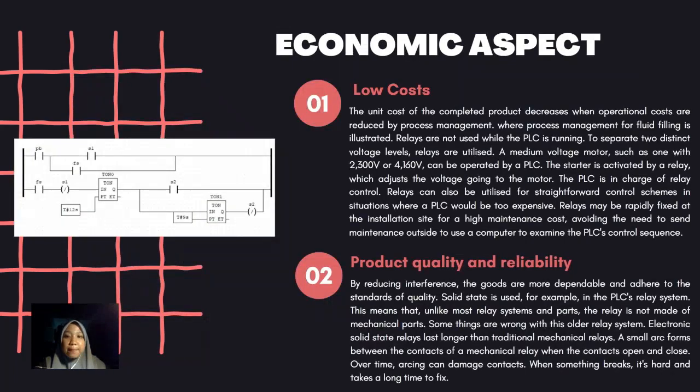Next, presenting the economic aspect of the control process to make operation efficient and achieve cost effectiveness. Among them is low cost. Do not use relays as long as the PLC is running, because the relay is controlled by the PLC. Relays can also be used for simple control schemes where a PLC would be uneconomical.